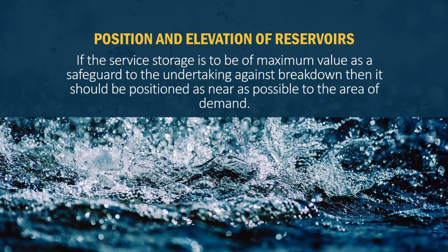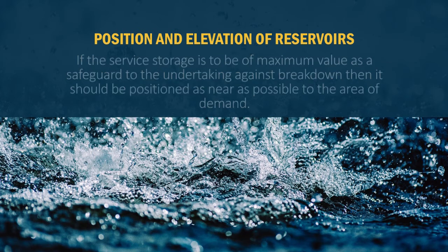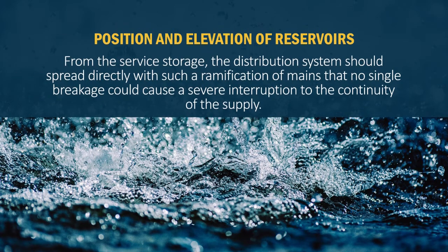Position and elevation of reservoirs. If the service storage is to be of maximum value as a safeguard to the undertaking against breakdown, then it should be positioned as near as possible to the area of demand. From the service storage, the distribution system should spread directly with such a ramification of mains that no single breakage could cause a severe interruption to the continuity of the supply.